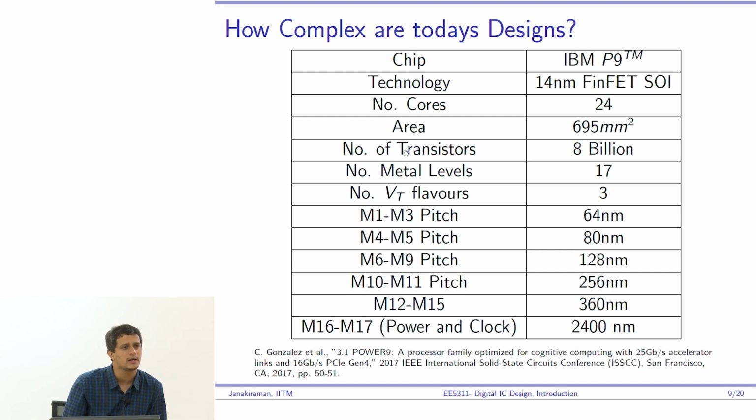And what does this contain? 8 billion transistors. Okay, so now if the on current of a transistor is a microamp, and the off current, as I told you, is a thousandth, right? Nanoamp. Why is the off current even a cause for concern? It's a nanoamp, right?